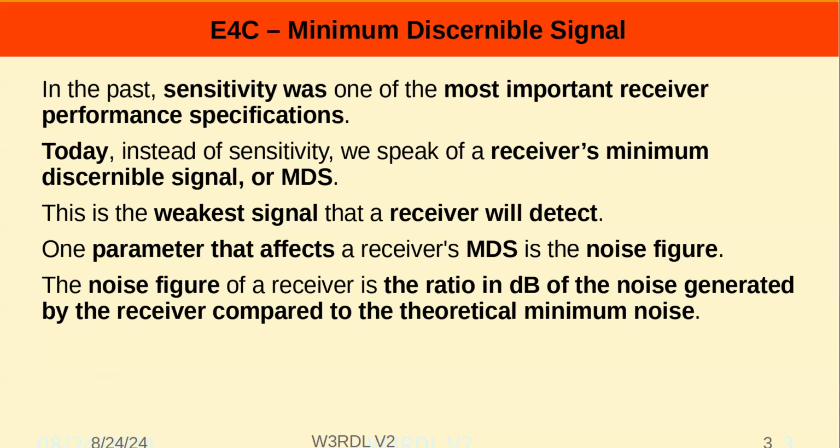Definitely it would have an effect. The more internal noise your radio has, the worse the noise figure is going to be, which means effectively you're raising the noise floor up. So on the digital modes, a lot of times we'll be able to detect a signal that's 20 dB below the noise floor, but that's not the theoretical noise floor. That's the noise floor in the receiver, in the system itself. It's also a function of how wide your bandwidth is, because the wider the bandwidth, the more of that noise floor power is part of the signal.